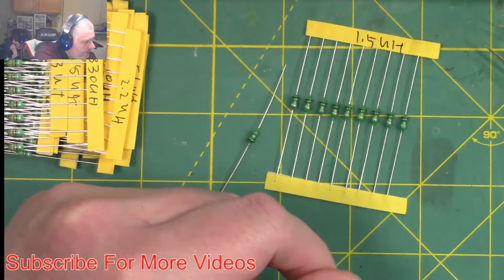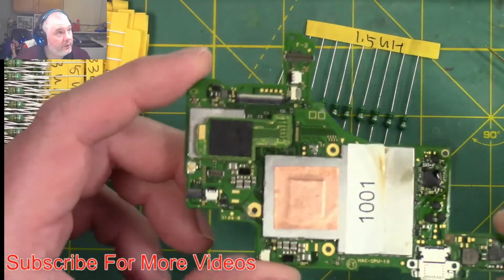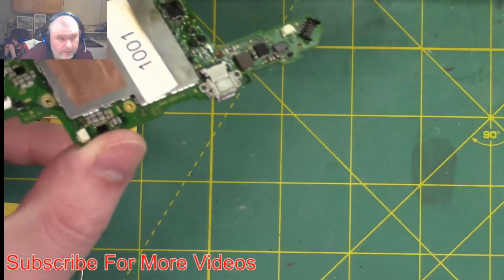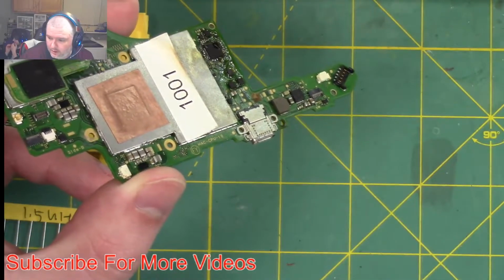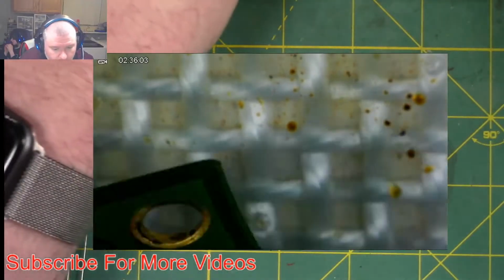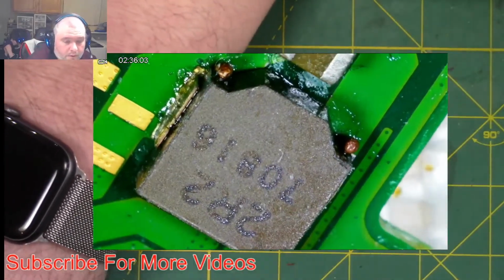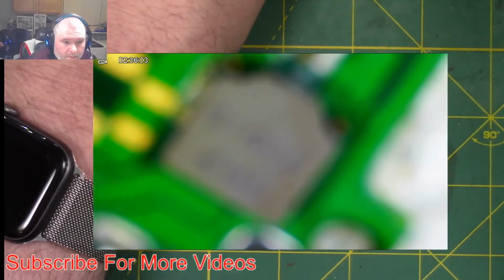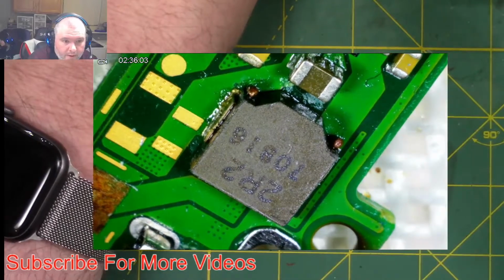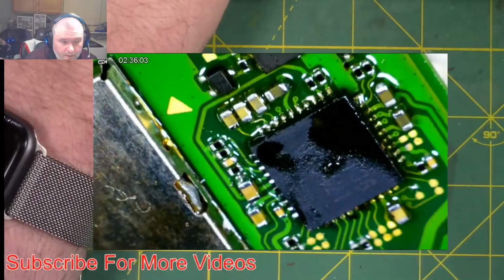And then also, if you take a look, this is a Nintendo Switch board, and you can see that there are inductors that are used. Let's put this on this screen here, and I'll show you some inductors. Down here is an inductor. This is used for part of the battery management circuit. This is going to boost up the voltage from the battery to the rail voltage for the Nintendo Switch.